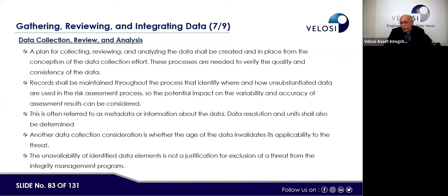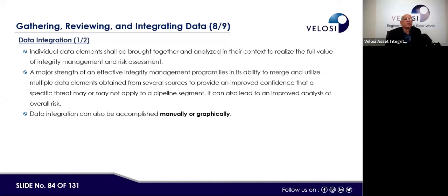And if we want to organize metal losses by ILI survey or by direct wall thickness surveys, then by having that data, and if we have to make a minimum thickness requirement, wherever thicknesses are lost more than the acceptable limit, then we may have to take certain corrective actions. So all those positions can be shown by the analysis of the data and by the review of the data.